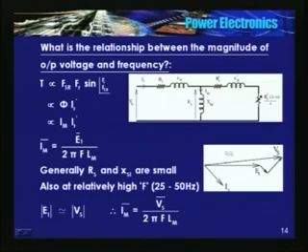I have just drawn a vector diagram, maybe a bit exaggerated. I am taking E1 as reference, and Is is a lagging current, because current has to be lagging in an induction machine. Then Is Rs, Is into Xsl, and this is Vs. So the magnitude of V1 is approximately equal to the magnitude of Vs, because these parameters are very small.